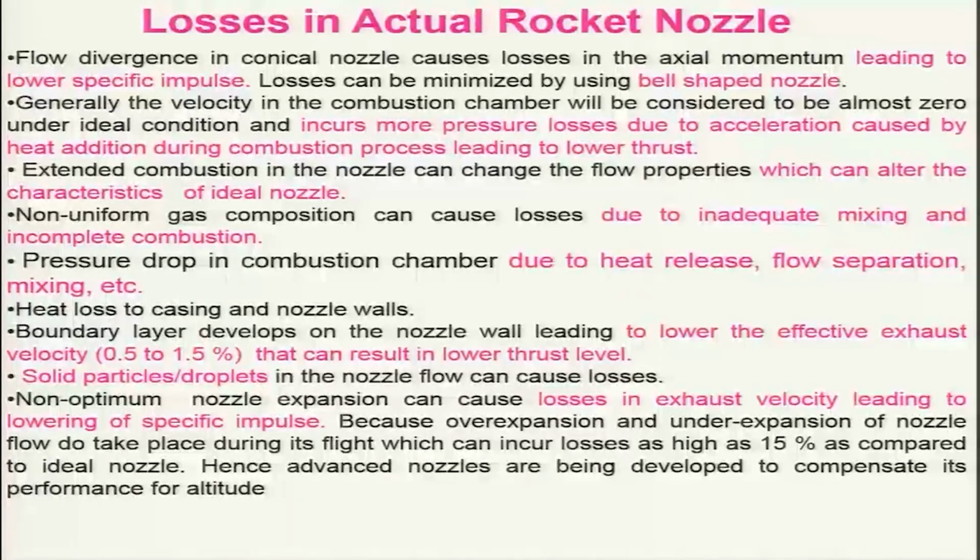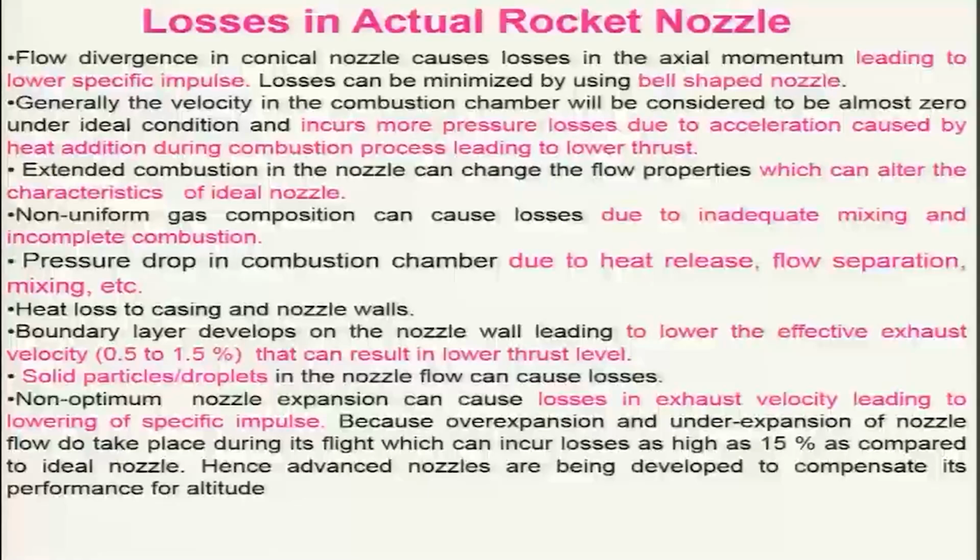As I told you, a particular nozzle will be designed for a particular altitude, however one has to travel through various altitudes. So the nozzle is subjected to over expansion and under expansion during its flight, incurring losses as high as 15% compared to the ideal nozzle. Hence advanced nozzles are being developed to compensate its performance for altitude, which we will discuss a little bit in today's lecture.